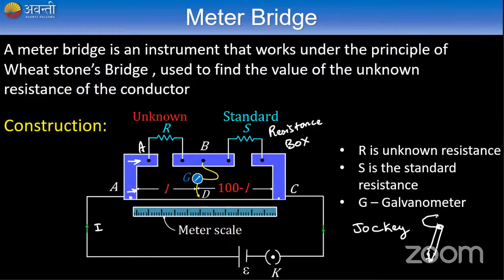If we use the color coded resistors, there will be 5% and 10% error, right? In our calculations we should consider that error. When we are calculating S, we have to consider that error also. That way, the value of the unknown resistance will also contain some error. So to avoid that error, we don't use the carbon resistors. Okay, got it?